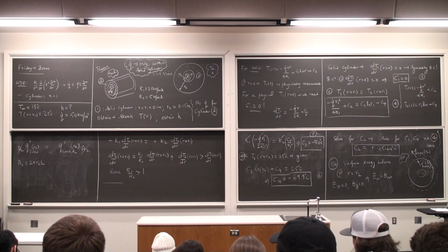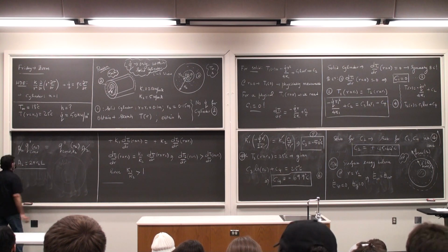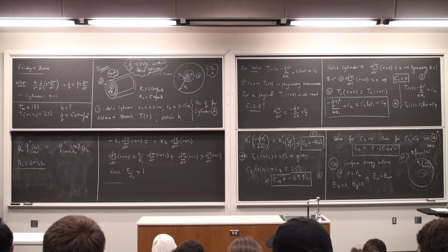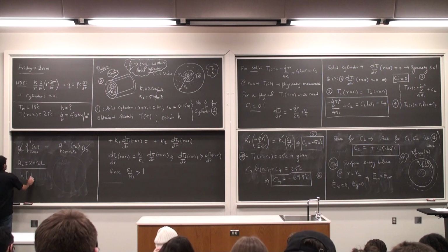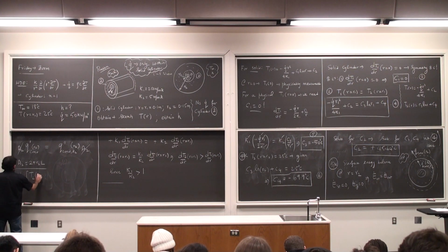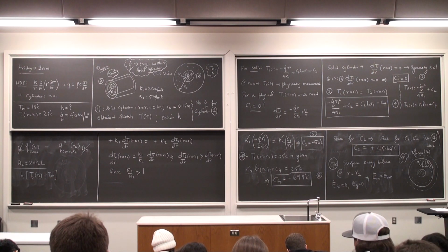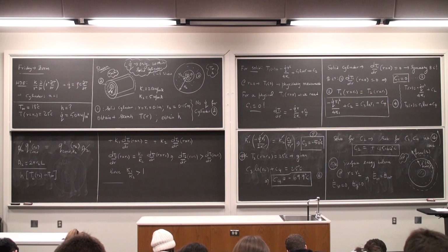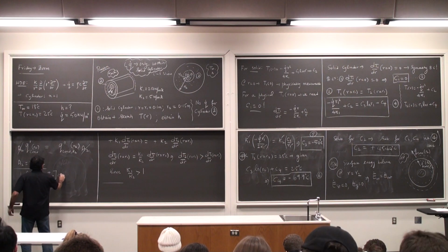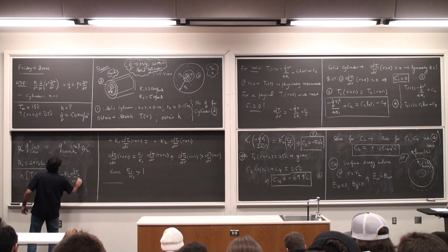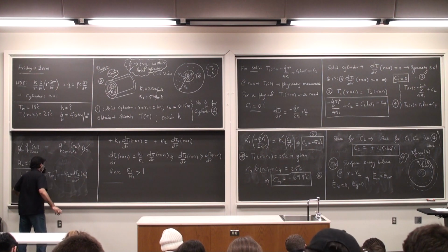Okay? And substitute. Convective heat flux coming from the temperature T2 at R2 onto the ambient. So this is H times T2 at R2 minus T infinity. Be careful, the conductive heat flux has a negative sign, so minus K2 dT2 by dr at R2.